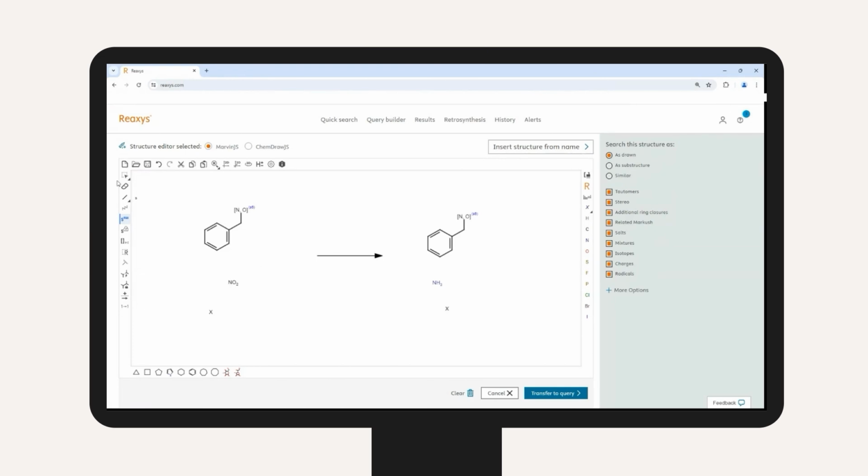Now the nitro group obviously needs also to be attached to something, so we can connect this here and also with our halide. So in this instance, as a shortcut, if I type R on my keypad, I'm going to put an R group in here. I can go to the select SMART R group here, but in terms of speed, this is also useful and quicker. Now I also need to define R in my molecule.